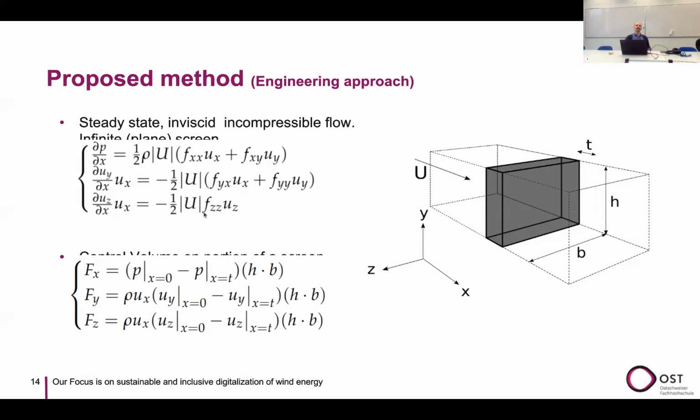What we can do is put a screen in a duct, measure these forces, and then using the analytical equations, fit the flow so that these coefficients would fit all the forces. So unlike before, where we had only one coefficient, here we get all the coefficients. So does this work?